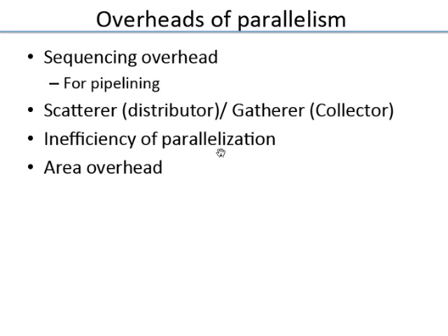And of course, you might not be able to parallelize. What if you cannot parallelize? Maybe you don't have enough parallelism. Then the extra cores are just sitting idle. So there is a certain inefficiency because of that. And finally, to come back and answer the question which was raised earlier, why not go 100, why not go 1000? The other important consideration is area. Clearly there is an area hit out here. You are doubling the area, and as I said, area translates to money.